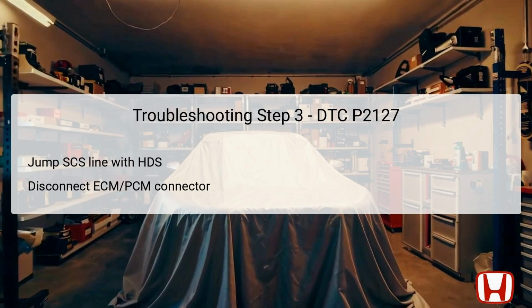This step is crucial as it allows the technician to assess the continuity of the circuits without interference from the ECM or PCM. Continuity testing will help determine whether any wiring issues exist between the APP sensor and the ECM/PCM. Maintaining safety is paramount during this process, ensuring that all electrical systems are properly managed and isolated before proceeding.